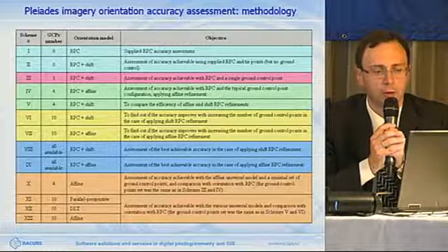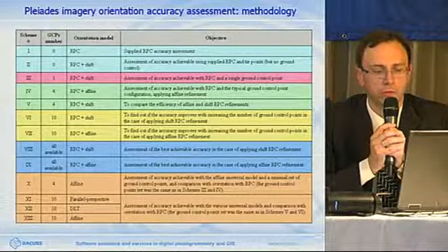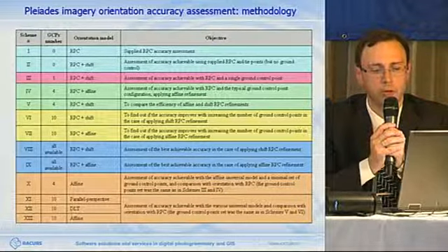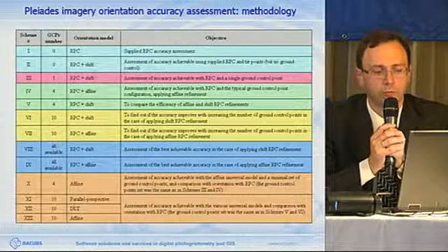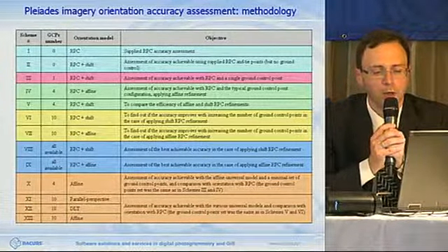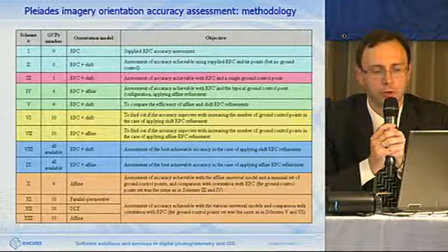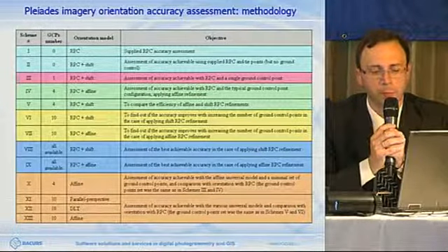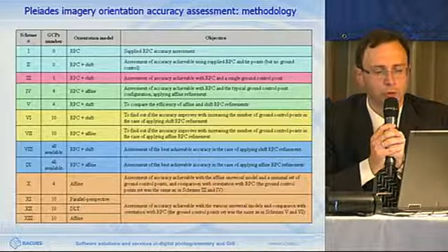The first group, the first and second experiments, were about identification of the achievable accuracy without the use of GCP, and the third experiment was when we have only 1 GCP. Next, the green group, the fourth and fifth experiments, use the number of GCPs which is usually sufficient and optimal for rectification of an image on RPC.